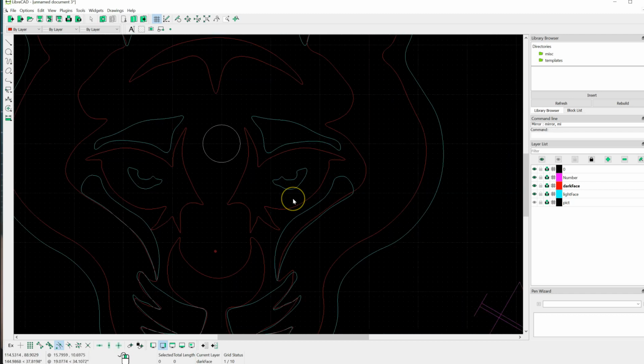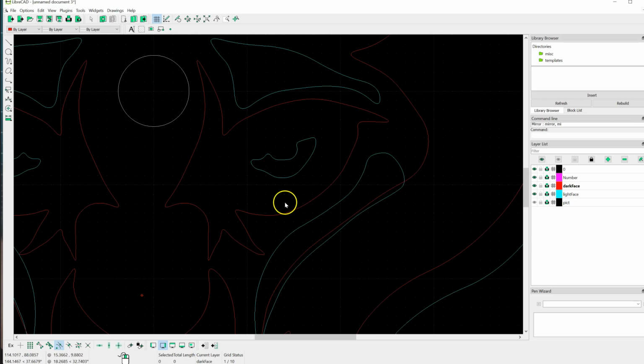Now if we look at this, you'll see that normally if I select something like this, it goes completely to dashed lines, all right? But if I select this now, it doesn't, because there's two copies. So let me uncheck that and go to my properties.